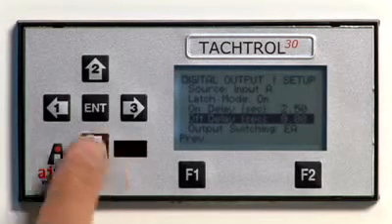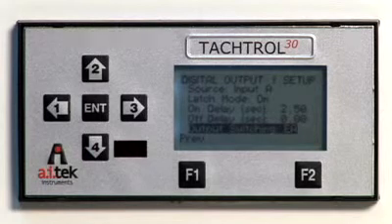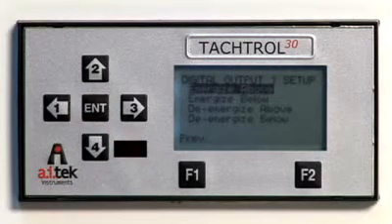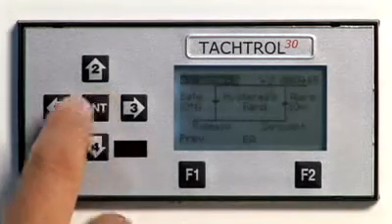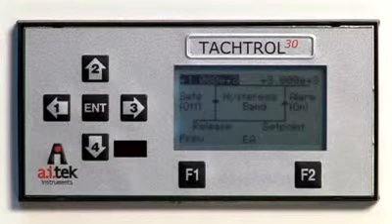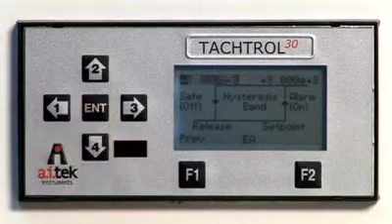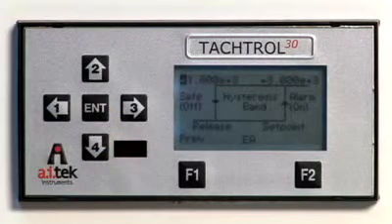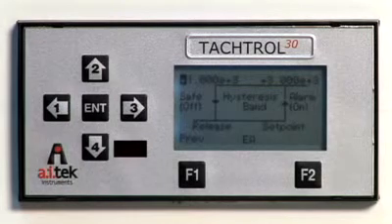Press the down arrow to highlight Output Switching. Press Enter. Select Energize Above by pressing Enter. The switching range information is displayed and Safe Set Point is highlighted. Press Enter to make active for change. Using the up-down arrows, we will change the set point to be plus 4,000.